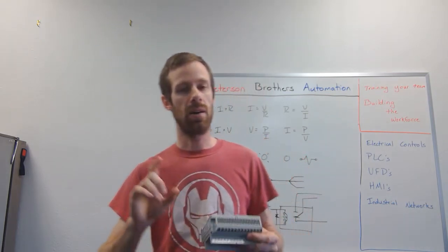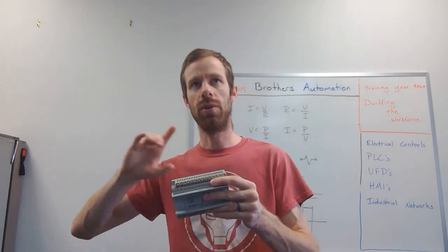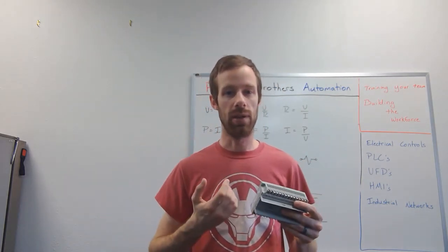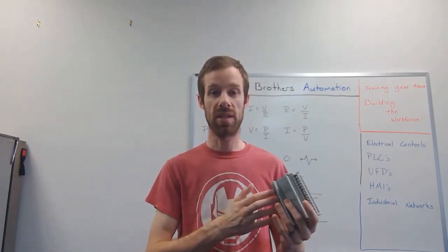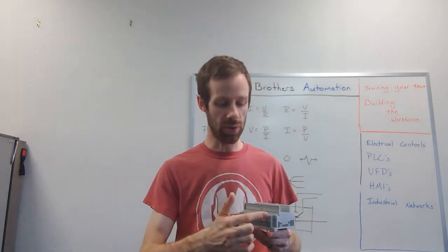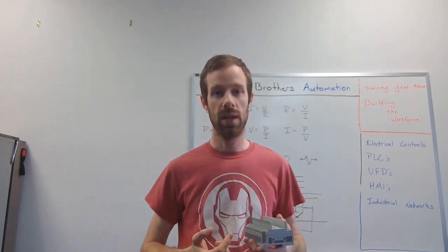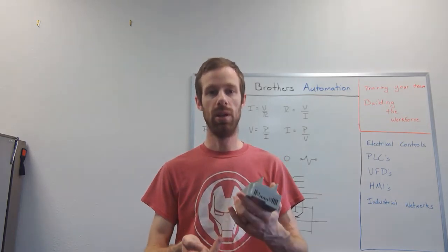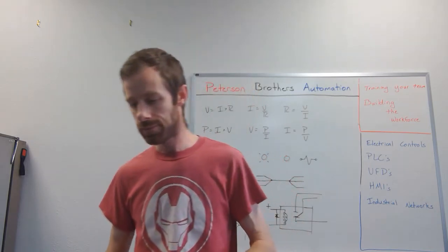So that means now that we're allowing the programmable logic control to turn the electrical energy into information. The program inside of it then converts that information into decisions. Those logical decisions drive all of the stuff that's connected to the outputs. So for that reason, we can program it. So we call it a programmable logic controller because it makes decisions based on logic.